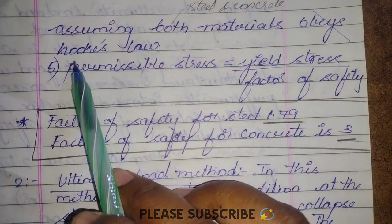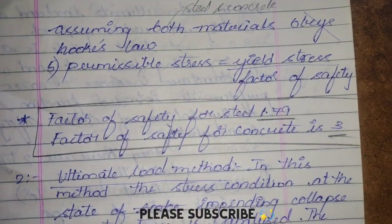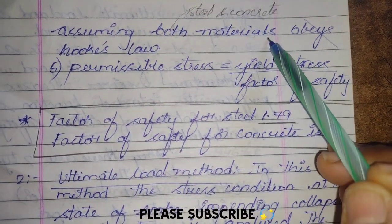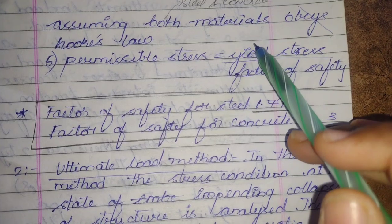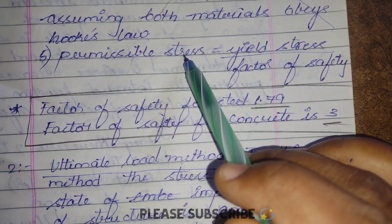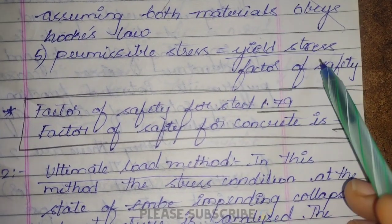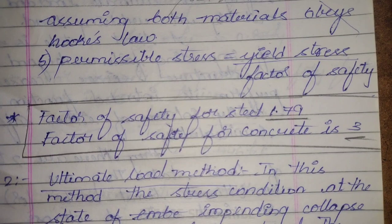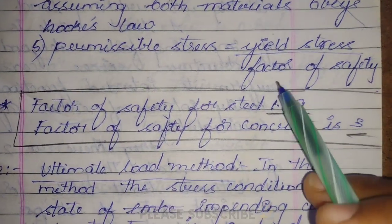And here we are assuming both materials, steel and concrete. We are discussing RCC members, which is why we mention steel and concrete. Here we are assuming both materials obey Hooke's law. We know Hooke's law, right? The permissible stress is equal to yield stress divided by the factor of safety. Remember, whenever we analyze any member, we take the permissible stress as yield stress by the factor of safety.